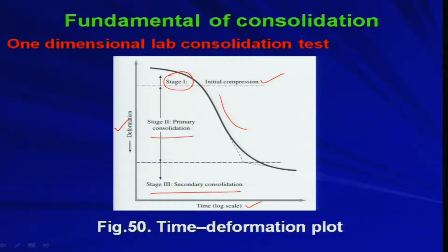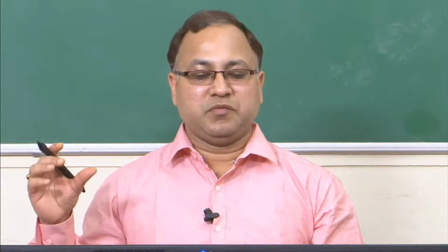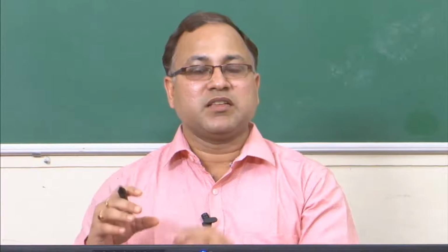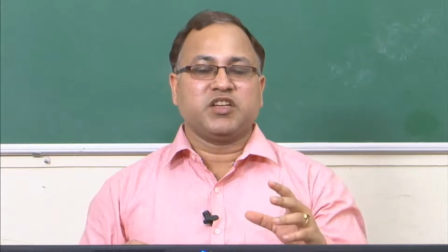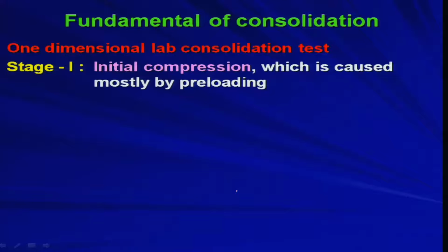Even after t is equal to infinity or 24 hours, still you will be getting some amount of settlement, though that is not a very significant amount, but you will be getting still some deformation in the soil matrix, because you will be getting some reorientation or the plastic orientation of the matrix. So, I mean soil fabrics. So, we will see that. So, stage 1 initial compression, which is caused mostly by preloading. So, immediately you apply the load, you will be getting the initial compression.